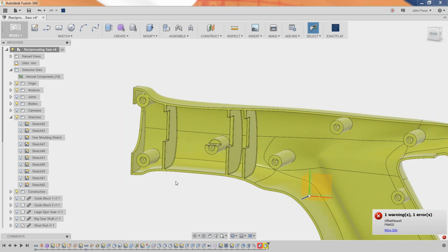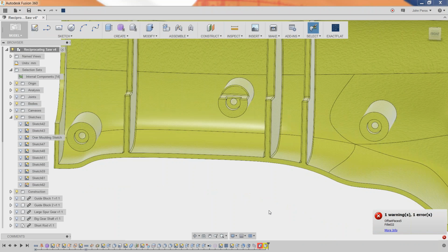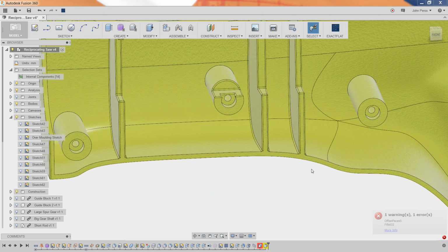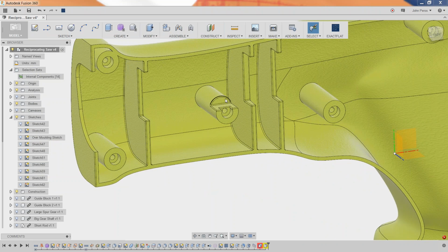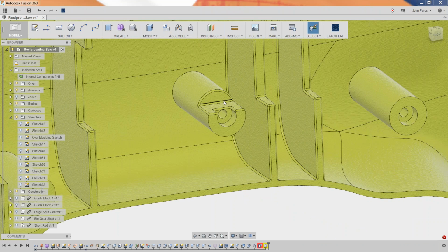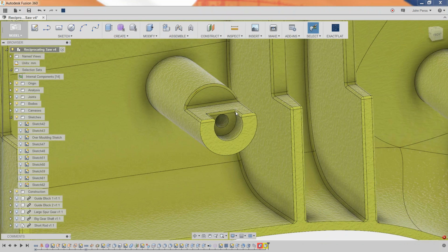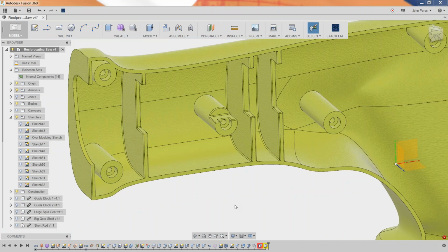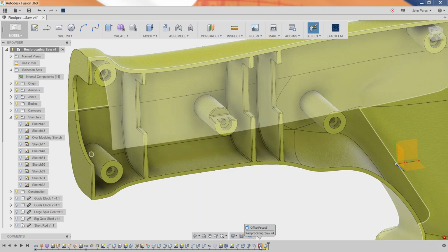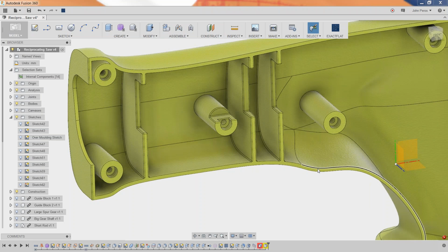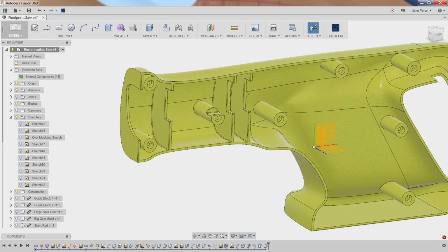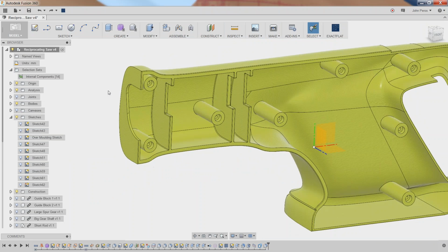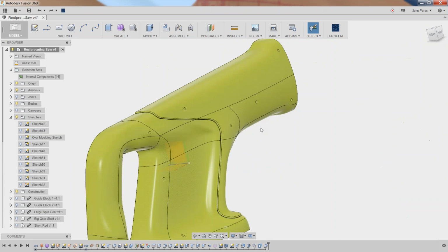And you'll see what happened now is my fillet thinks that these edges are a part of it because that cut moved down. We moved the face down, it moved the cut down. It's now filleting the edges on the boss as well. And so Fusion is just calculating all this stuff. And even though I've got an error here, it's still rebuilding everything for me as it should. So go back now, just our normal tool, and I'm going to show you some other stuff.